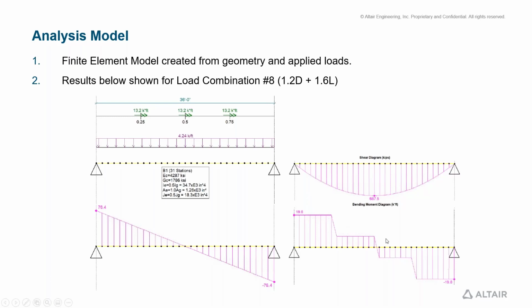Now it's worth mentioning here that girder supports, by their nature, are pin supports in this structural model. The girder is not going to have any torsional resistance. So the critical sections for design are taken at the face of the girder, which is 12 inches at each end from the full span length. That might come up in some of the later calculations, so I did want to mention that before we get too far along.